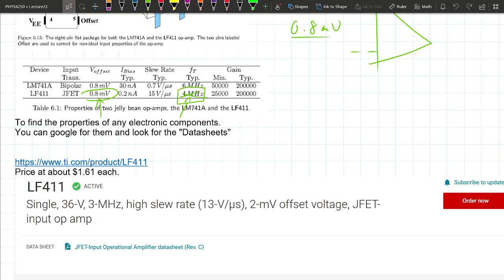All right. Where's the gain bandwidth product? You guys see it? It should have units of hertz. Usually what I do is look on the right-hand side for stuff that has the right units for me to look at and figure out what I need to find. There was hertz under the slew.